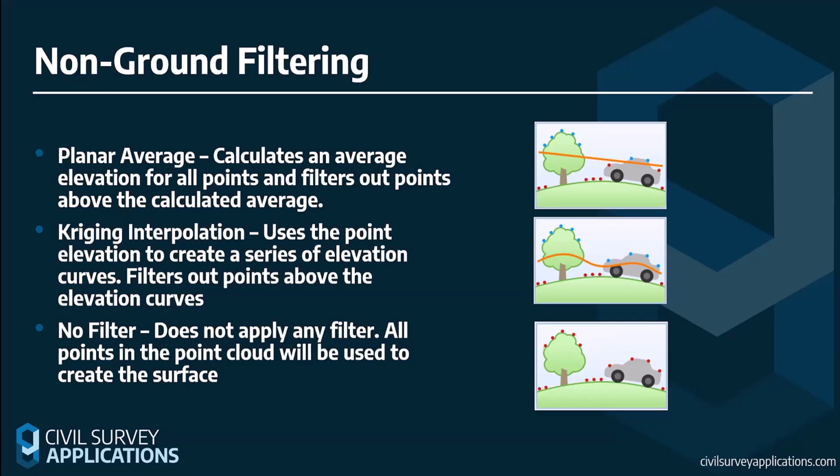It'll create a surface at every single point in your point cloud, unless you're picking up something relatively flat with no major change in elevation, or you've done an extremely good job of cropping and deleting your points. I would not recommend no filter as an option. But this is my opinion. If you like using one of these methods over the other, don't hesitate to use it. They are all very good tools to use.